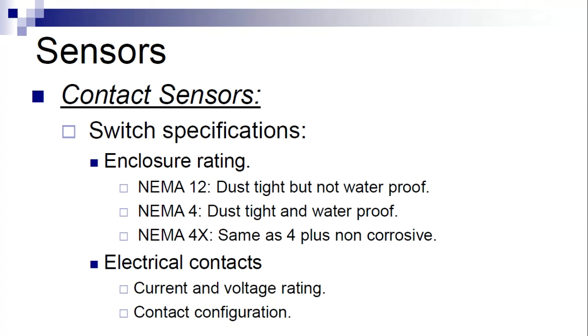Okay, so officially NEMA stands for National Electrical Manufacturers Association, and they work with some others to set these various types of standards. So you should be aware that NEMA is used to set standards for enclosures. If you were putting this switch outside or somewhere where it's going to get wet, maybe in a car wash, then obviously a NEMA 12 would not work because it's not waterproof.